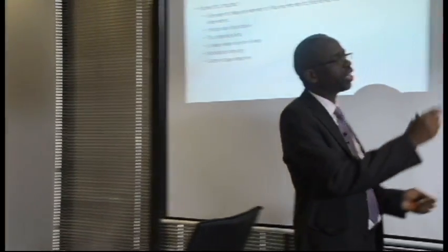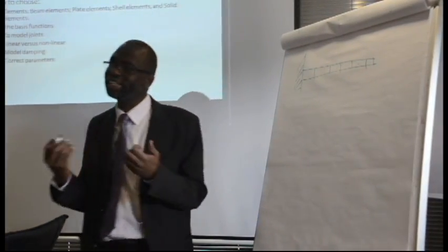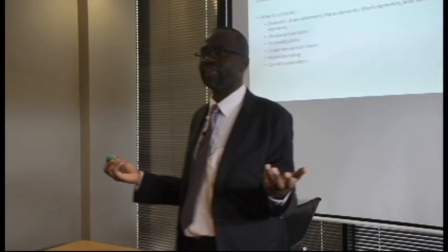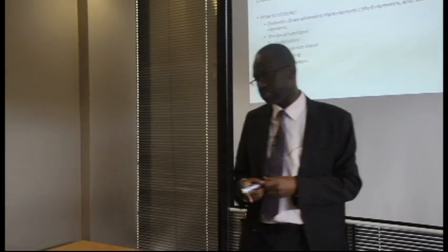The other problem that you will have to deal with is, how do you model the joints? Complicated structures or shapes, how do you model them? Do you use a linear or non-linear finite element model? The one that I have just written is actually a linear second order differential equation. But if the system is complex, for example, it's made out of plastic instead of aluminum, then it's probably non-linear and your equations become more complicated.